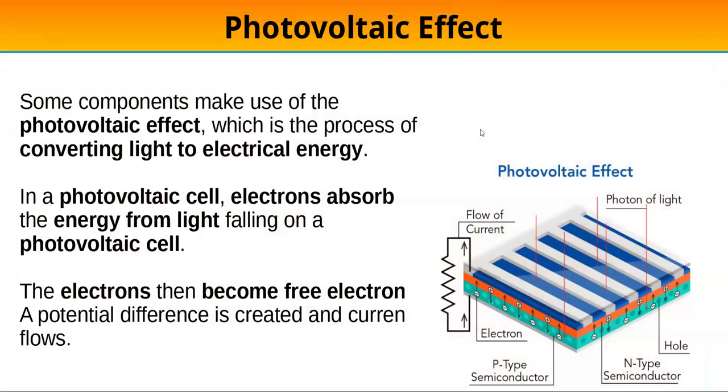So there's this thing called the photovoltaic effect, where you make use of p-n junctions and let light shine on them, and it can actually cause current to flow through the junction. Those photons that are hitting it can have enough energy to create free electrons that can do the migration and create that current flow. So it's a special kind of diode, and normally they're made from silicon.